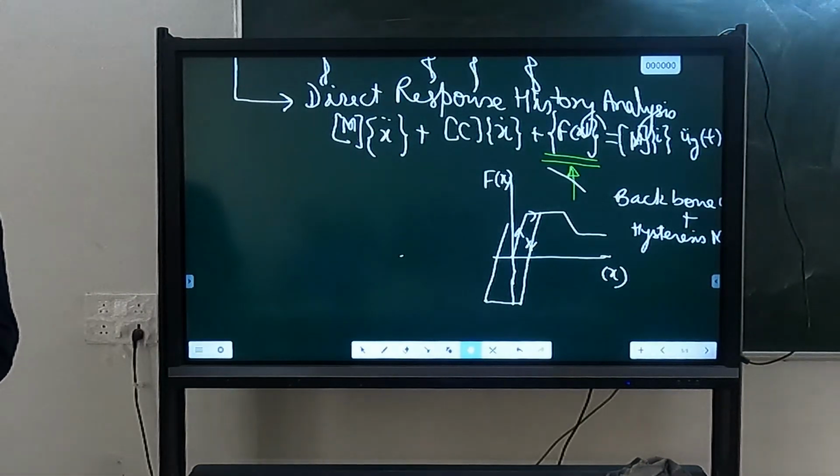The difference is more because of the different history of loading. Non-linear behavior depends on history of loading. Linear behavior also depends on history of loading, but when our number of cycles is in millions, then it depends on the history of loading. Normally, if few cycles, it does not depend upon the history of loading. But non-linear behavior depends on history of loading even for few cycles.